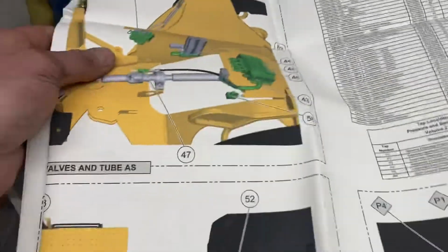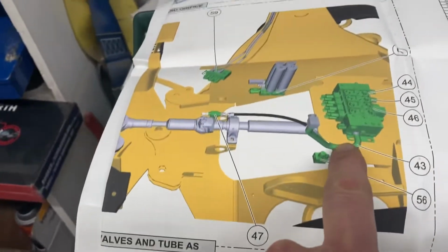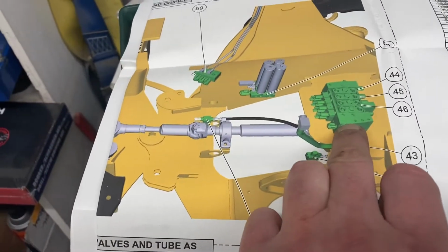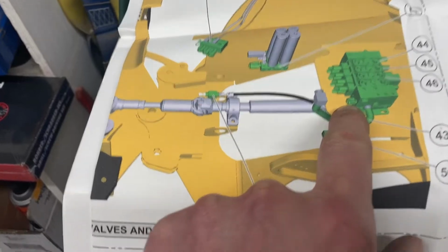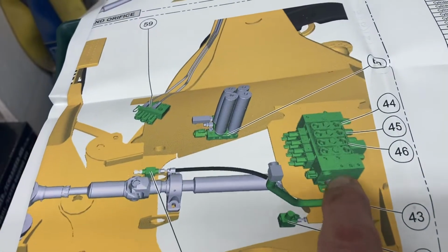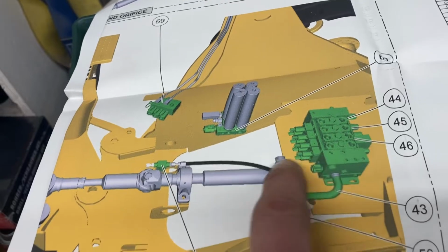One thing that I do like about Caterpillar manuals is they have really, really good schematics. So here's one here, but they're really big if you're using the actual hard copies, the paper copy. You can see how this thing folds out like 8 different ways. But here it is right here. This still isn't the greatest illustration of it, but you can see your accumulators and things. So this is your control valve for all your implements. And the lockout valve is this one right on the end, of course. That's your supply. That's why they call it lockout, but it supplies oil to all your function valves. So your tilt and your boom up and your auxiliary valve are all in here.